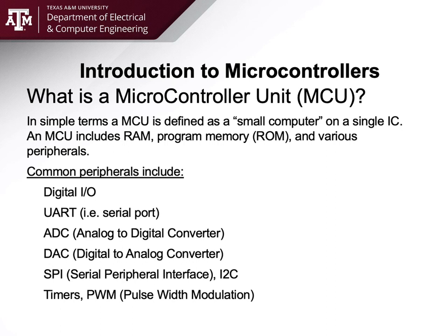And then vice versa is a digital to analog converter. You have some numerically computed value. You now need to represent it as a voltage, maybe to drive an amplifier that's going to drive a speaker, or to drive a servo motor, or to drive a valve of some kind. In that case, you would actually be using a digital to analog converter to do that.